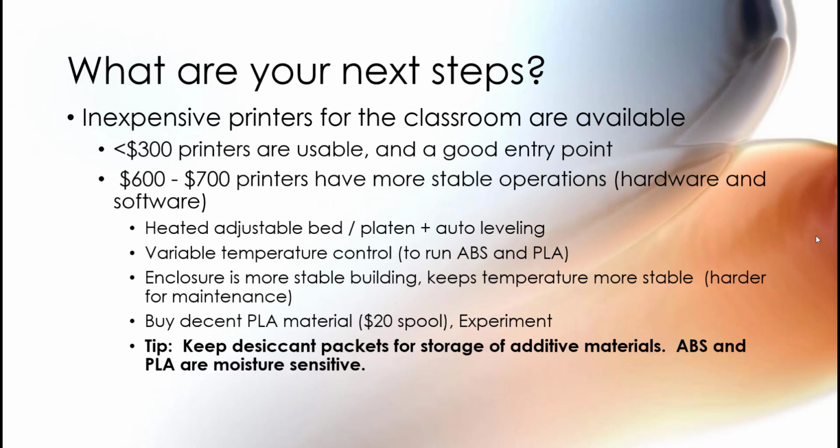Keep your desiccant packets, so when you have to Ziploc bag a material roll that you're finished using and changing the color or material, you can store it with some desiccant, because PLA and ABS are moisture sensitive, so you want to make sure that you maintain that moisture environment. Ed's got a great setup to do drying, and you could actually do that drying process in one of the food dehydrators and things like that. But again, desiccant packets are your first line of defense.